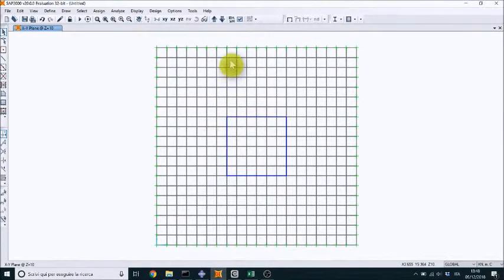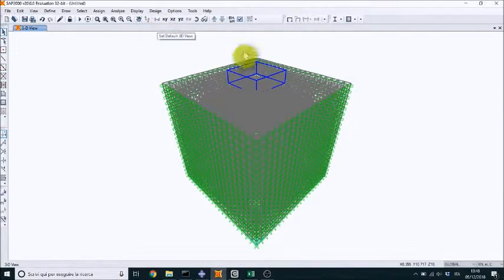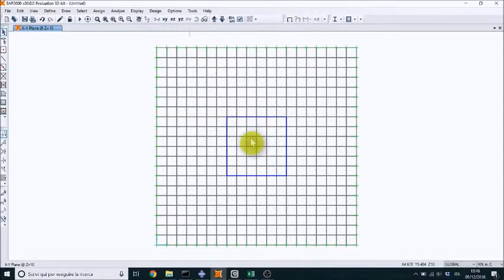Okay, if you want to look inside, we can go from 3.5 to 6.5 in the y direction or in the x direction, and you can see the section with the soil and the foundation. Okay, now we have the foundation and we have the soil. We have to divide the foundation into different elements, because if you do not divide the foundation, you will not have the communication between the elements of the foundation and the elements of the soil.